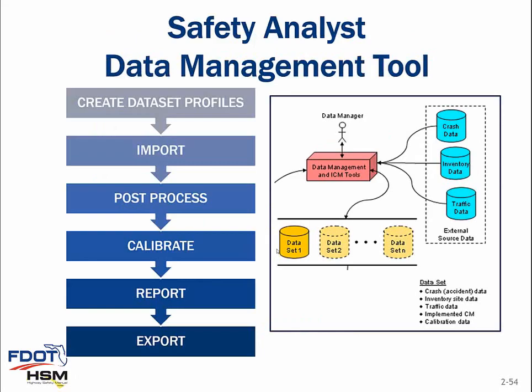The data management tool provides capabilities for highway agencies to create and maintain the Safety Analyst database, including data on crashes and the characteristics of roadway segments, intersections, and ramps. Within the data management tool, the user can create dataset profiles and import, post-process, and calibrate data. The user can also report and export the final datasets.